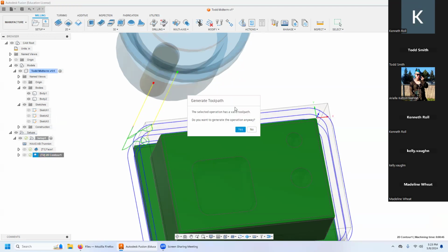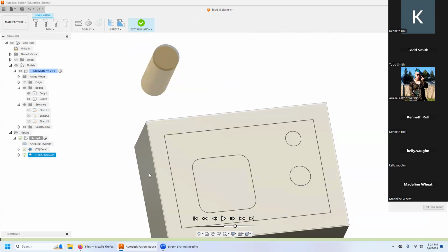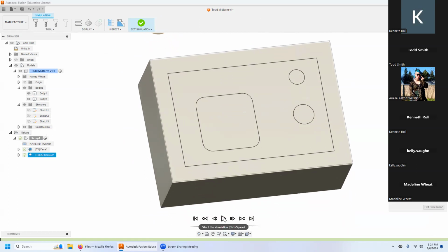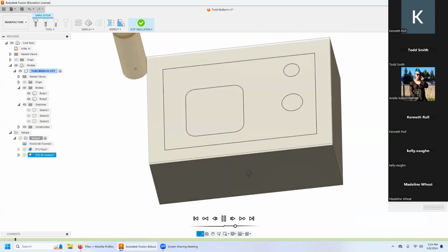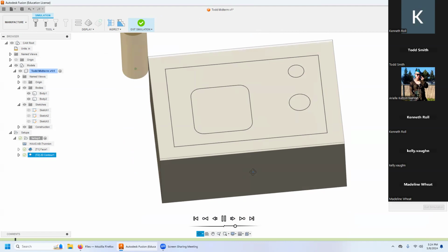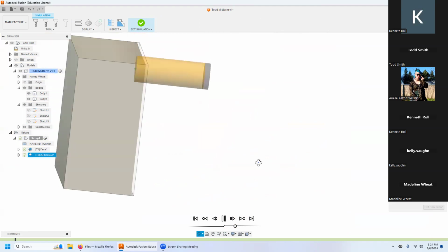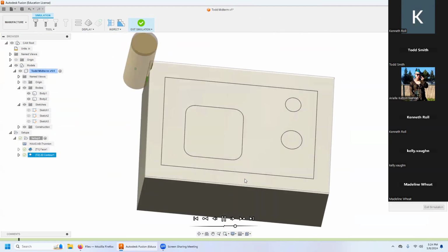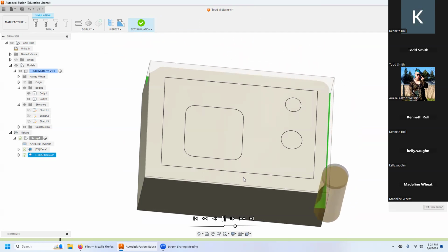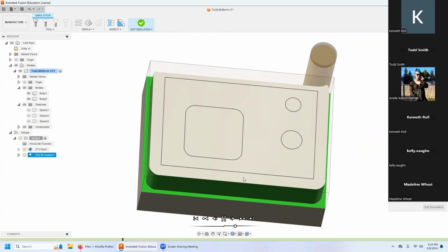Let's go to simulate, not edit. Stop it. There we go. Coming down in really close. Look at that. That is no good. It's really close to our stock. That's just not nice. Ooh, big heavy cut. Pow. It can theoretically take that, especially if it's in dovetails, but I think that's a little aggressive. Nice cuts after that, though.